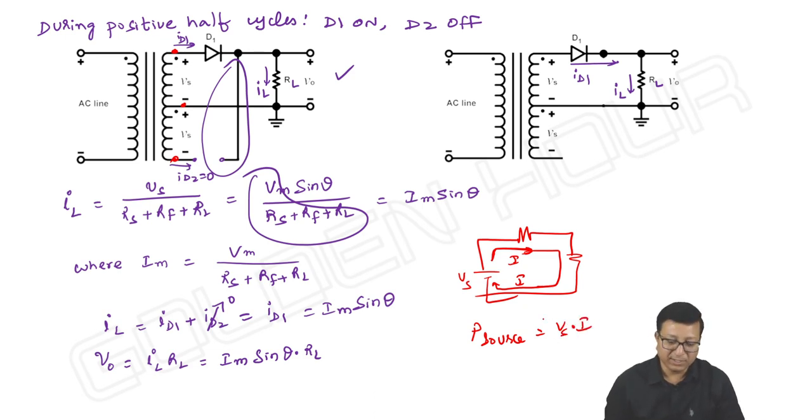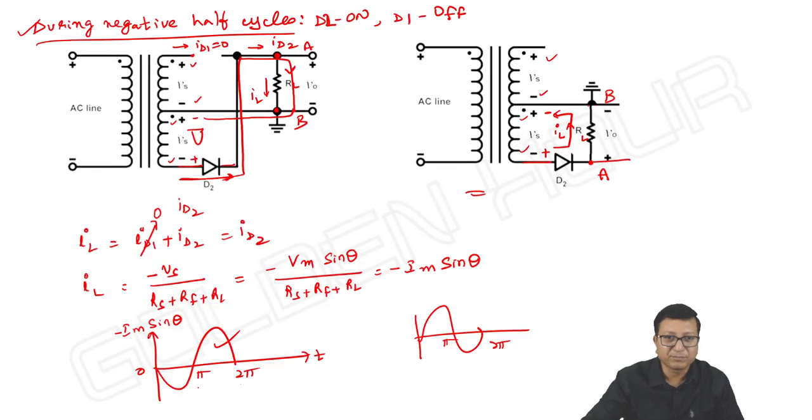Okay. But is there any such possibility to write here? Similar thing? No. Here the total voltage between the two ends of the secondary winding is 2 Vs and I cannot write it like 2 Vs into ID1. Of course, ID1 and IL are same here. Okay, wrong. Because positive cycles. Negative cycles, what happens? The same 2 Vs you can see.